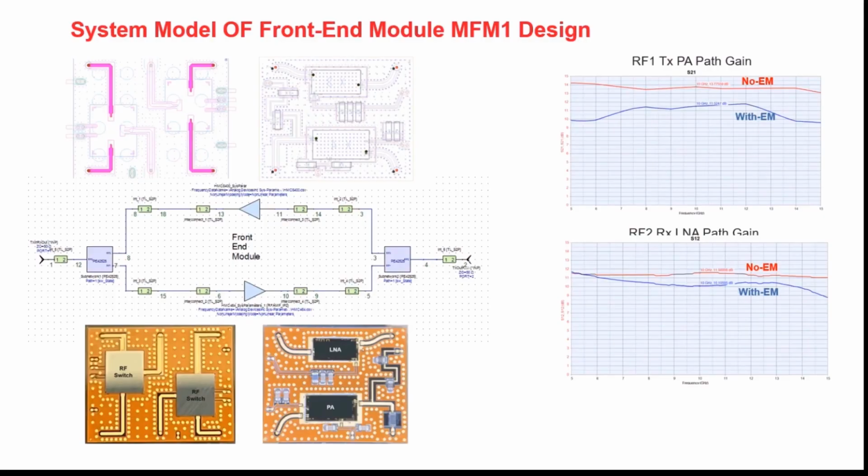What's unique here is we're going to reuse the electromagnetic simulations that Nate did, and we're going to select the specific nets that are the connections between all of these different circuit components. Once we've done that, we can actually extract the individual S parameters and load those directly into System View using a feature called EM Link. When that's done, we can simulate the overall circuit response with those electromagnetic effects.